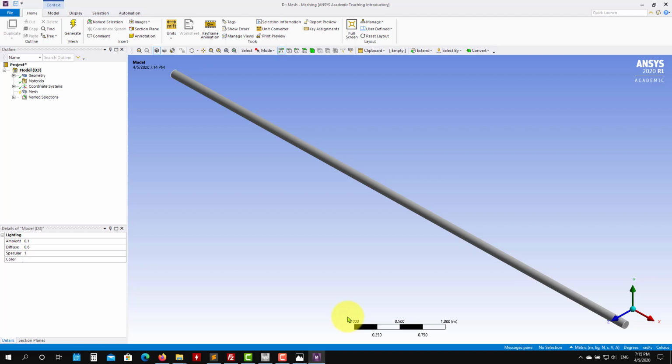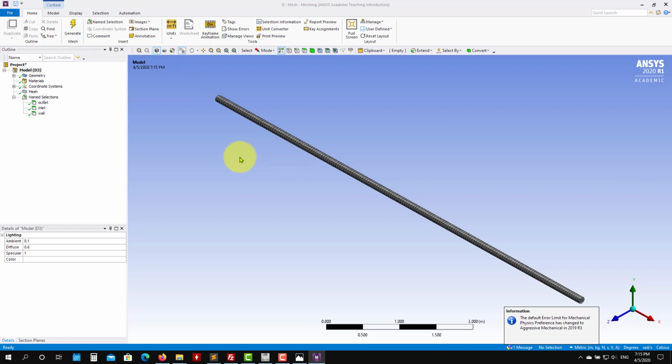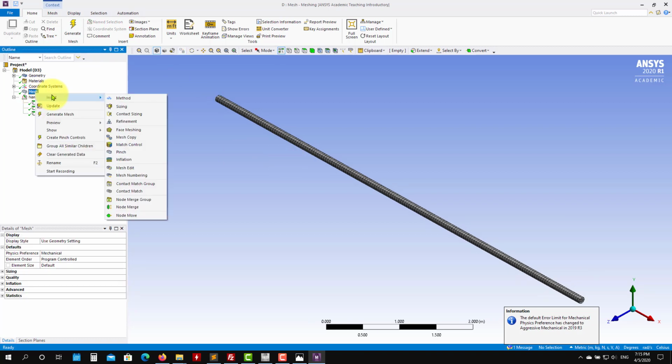And something very important also, with Fluent Meshing you cannot do 2D meshes. Instead, in Ansys Meshing you can do 2D meshes. So let's work here. We have the geometry. See that all the named selections that we have are already here. So generate. We're going to take the default parameters. We don't like those, so let's do what we did previously.